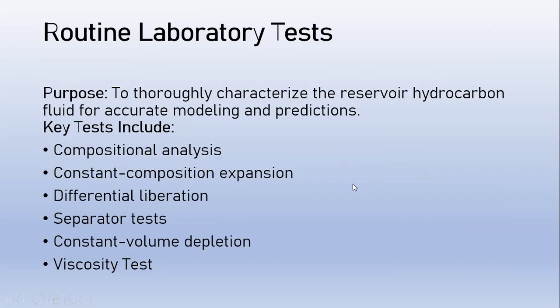For the routine laboratory tests, we have 6 experiments, or let me say 5. It depends on the type of fluid. If it's oil, we do composition analysis, constant composition expansion, differential liberation experiments, separator test, and viscosity tests.